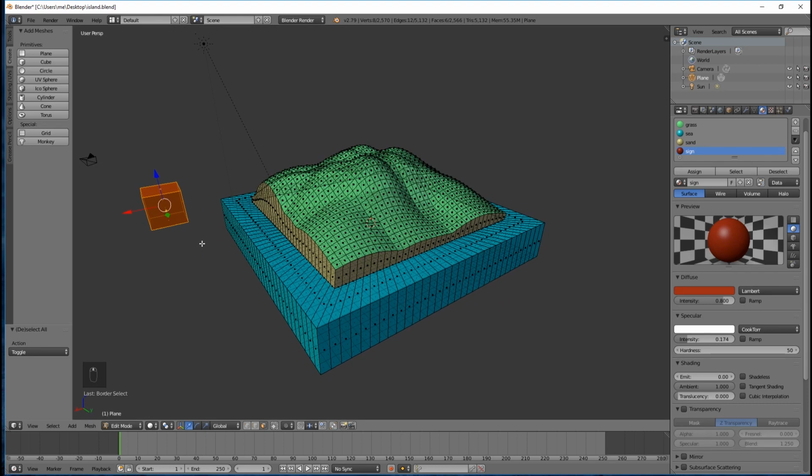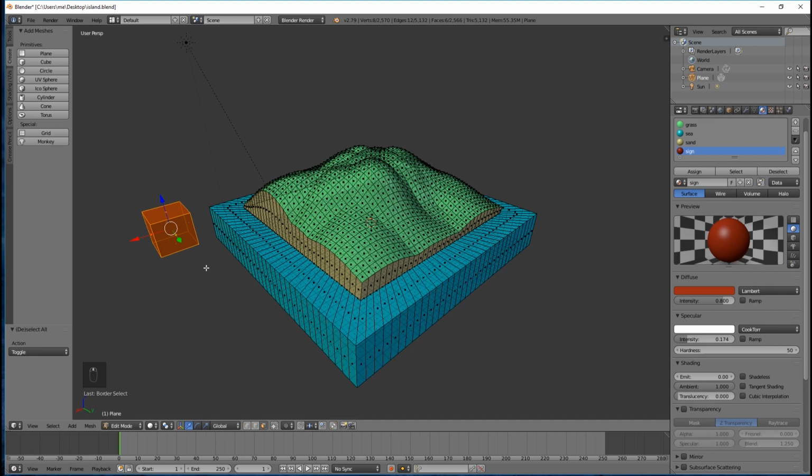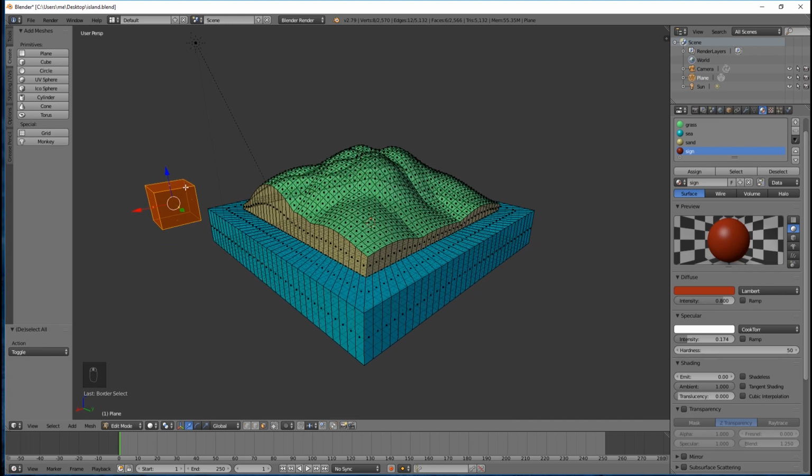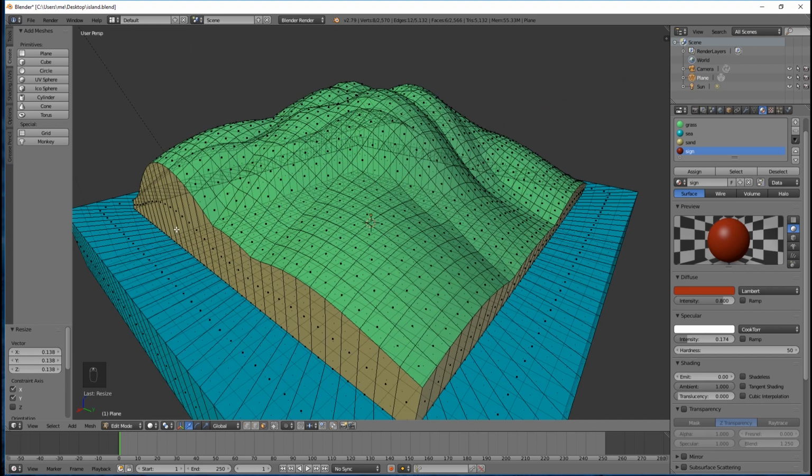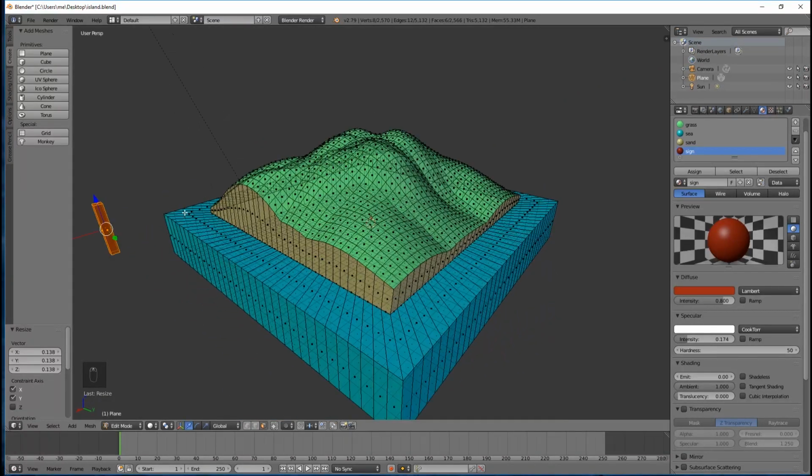So there we are. I've now selected the whole of that cube, and I need to now scale it. But I don't want to scale it on the vertical. What I want to do is scale it on the red and green axis, that's the X and Y axis, but I don't want to make it any smaller on the vertical axis. So I'm going to press S for scale, which will allow me to scale the whole thing up or down, but then I'm going to press Shift Z, which basically means scale it on everything except the Z axis. So you'll see it gets wider and deeper, but the height doesn't change. So I'm going to bring that down so it is sort of like a post. I'm going to just zoom in a little bit on that. I think that's about right, something like that.